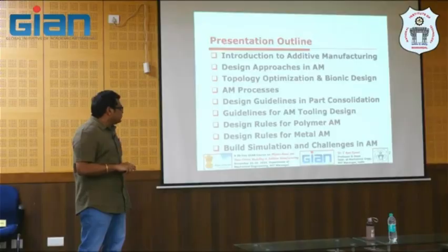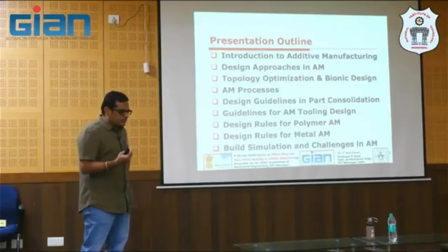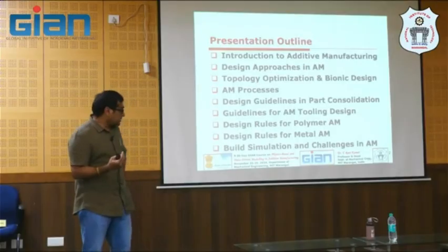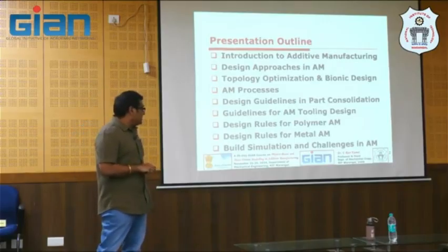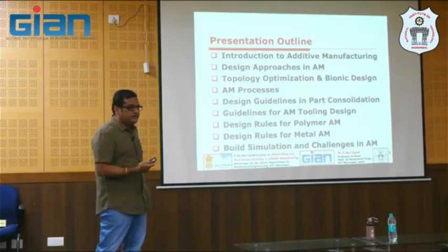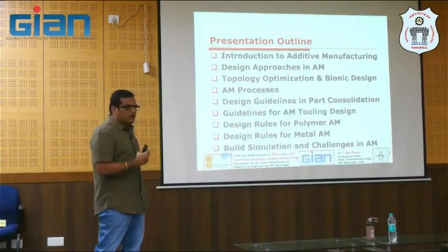And another one is the tooling area, right? So you have, say, injection molding dies, where you can make conformal cooling channels with additive manufacturing. We'll try to see some of the design guidelines in tool making or in designing the conformal cooling channels.